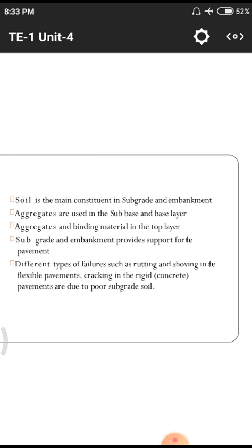Why? Because the total road has to bear a huge amount of compressive loads due to vehicular movements. Whenever a vehicle stands on a particular road, the total load has to dissipate into the soil through the base layers and sub base layers, so that those two have some quantity of compressive properties. So we construct the base layers and sub base layers with the help of aggregates. Normally we use coarse aggregates and coarse aggregate supplements. Why? Because they bear a huge amount of compressive loads.